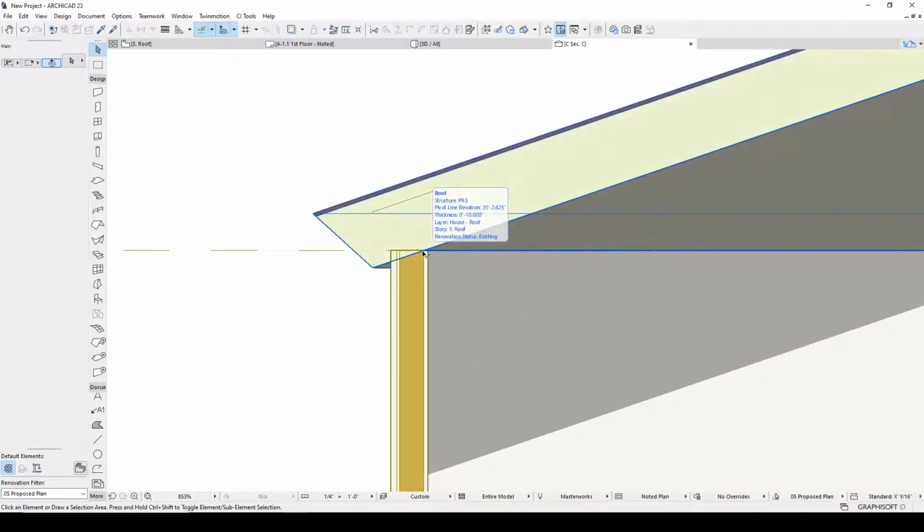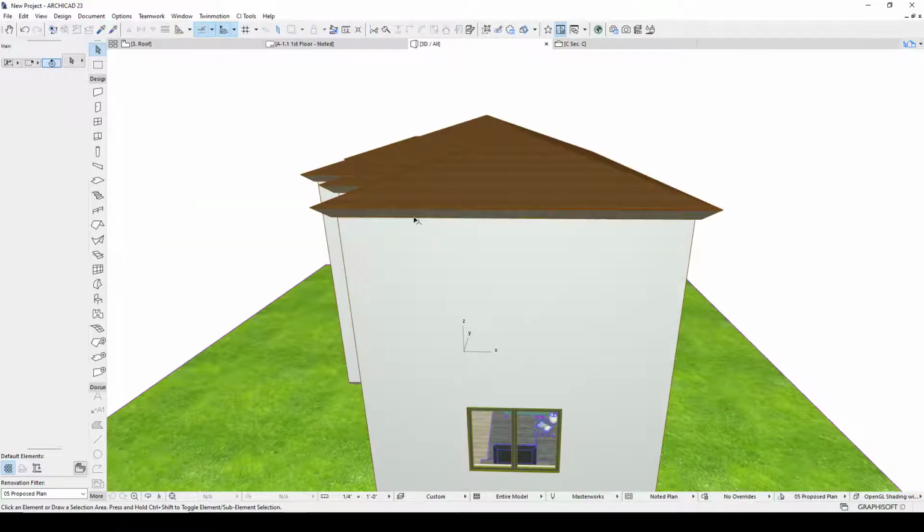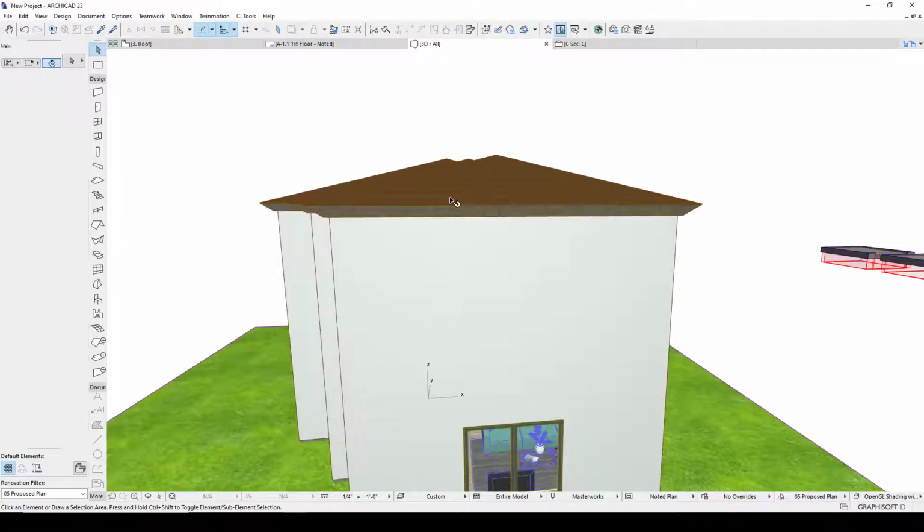Notice that the 16 inches is perfect. It's a horizontal dimension, and it's to the very tip of the plywood. So that's what's going on with that. Now, a couple of considerations. First one is I don't like using the roofs like this because it generally doesn't depict what I really want the roof to look like. The rafters and the fascia are generally not the same dimension. I may have rafter tails. I may have a boxed in soffit. None of those options are available if I do it with the roof only.